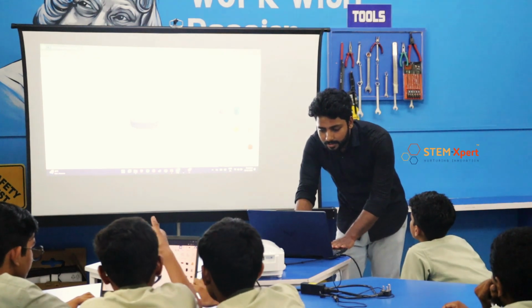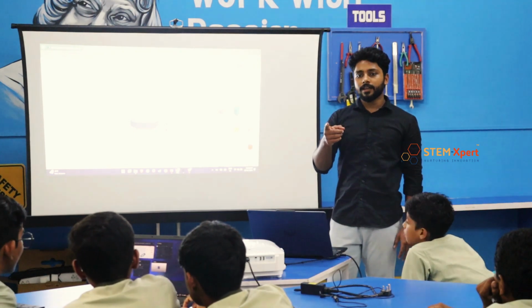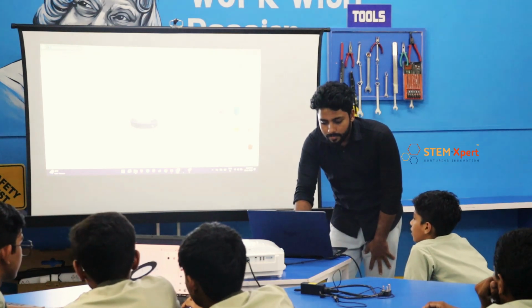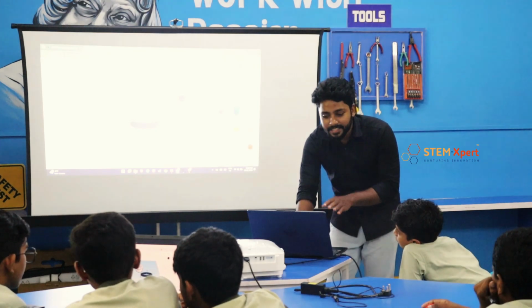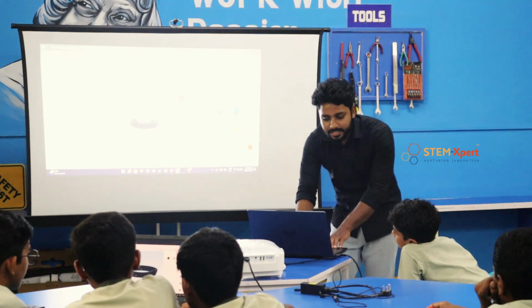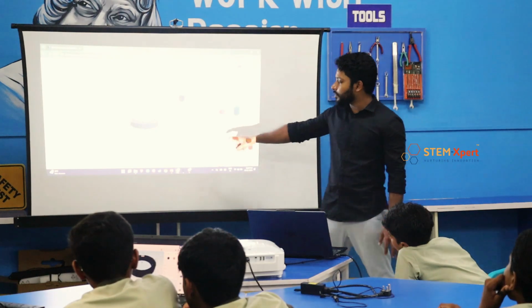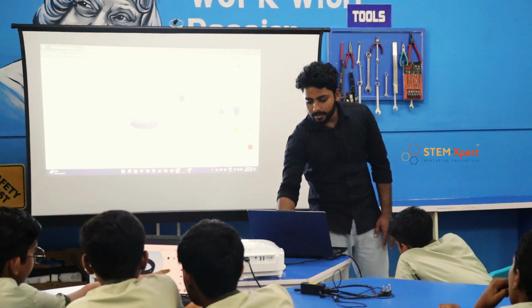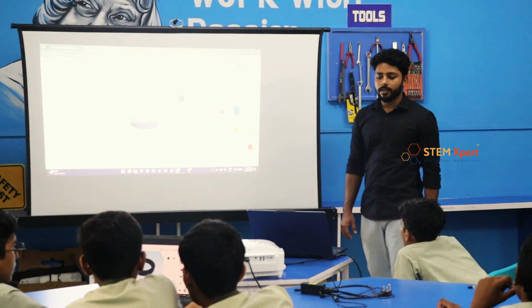Now let's go to the dimensions. You have done it, right? Okay. Now let's choose this one. Choose the tube, and here we are going to make the changes. Okay, let's change the wall thickness to around 8. Just change the wall thickness to 8. You can type 8.